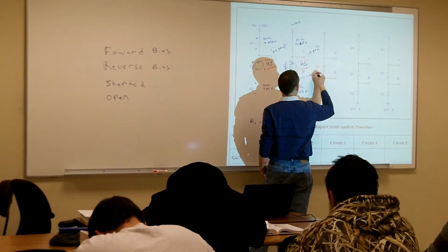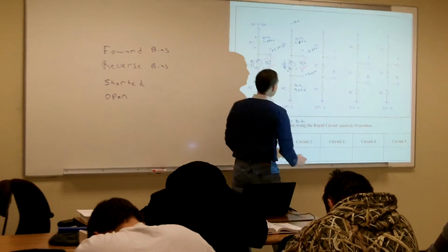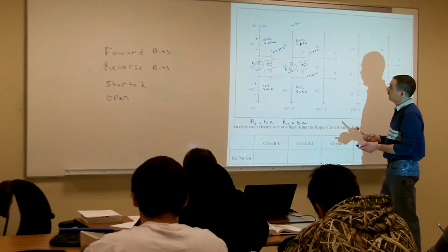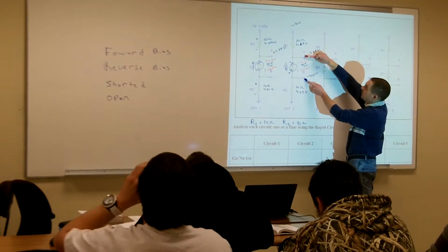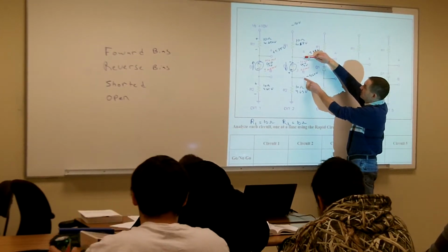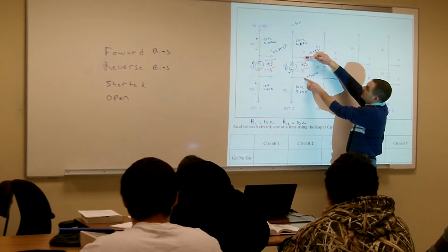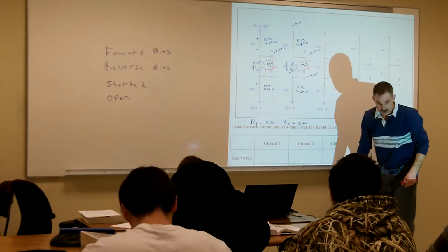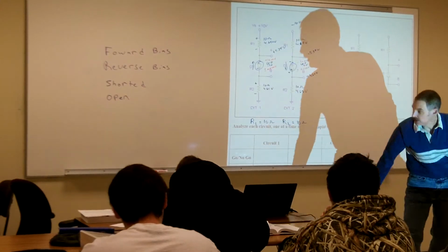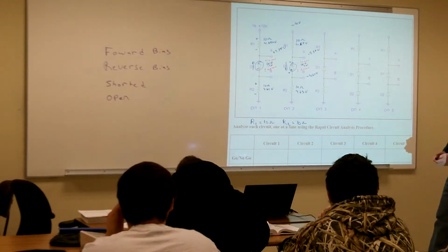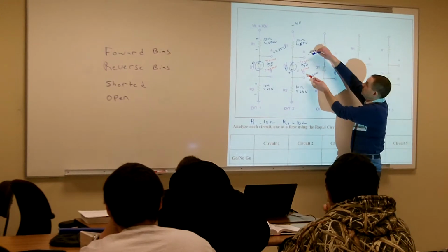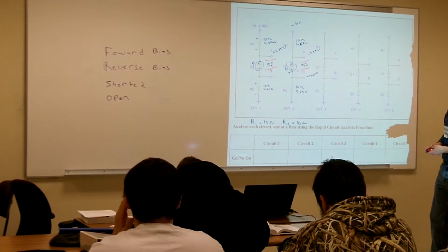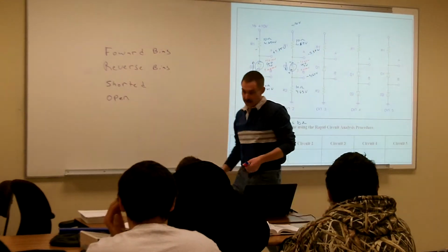And if you wanted to double check your work, if you went from test point A to test point B, what would I measure for voltage? Negative 0.7. So if you're double checking your test point voltages, you can always re-verify that you got that 0.7 difference between the two.